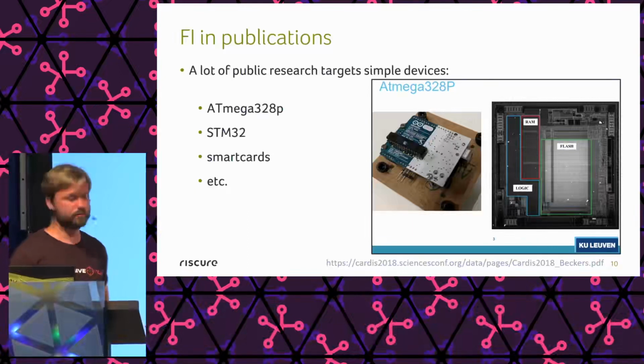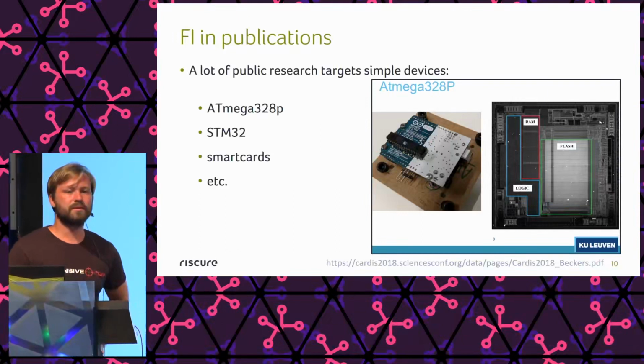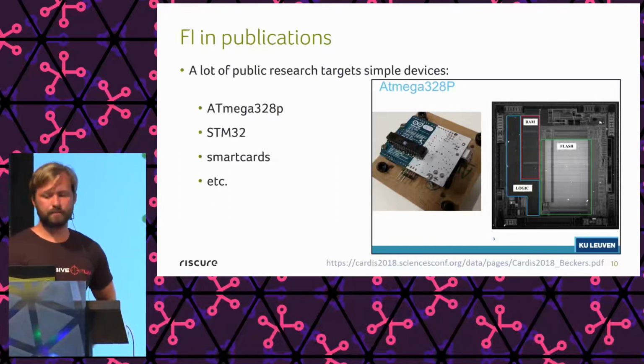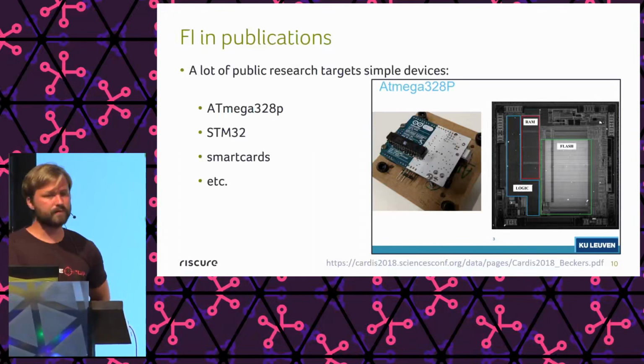There is more other research. For example, this was published at CARDIS a few years ago, which studied in depth a lot of different possible effects of laser fault injection on the ATmega328P chip, which is an 8-bit microcontroller from AVR, which is very simple.